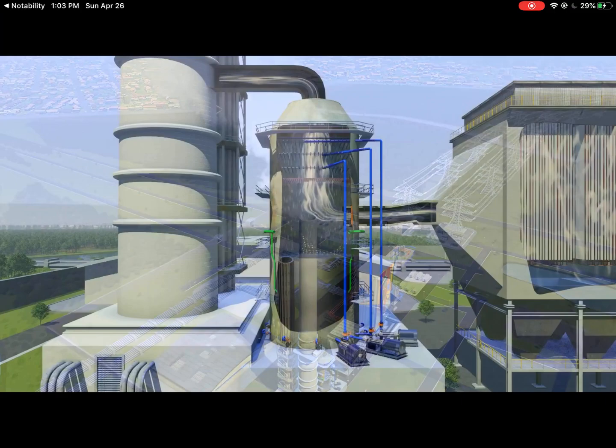So basically we're introducing the limestone or limestone slurry droplets from the top, and while these droplets fall downwards, they'll absorb the sulfur dioxide that's in the gas and then form some products. Finally, they'll settle down in this container. And then after we dry them, we can get gypsum. You can also see this device on the left, which is introducing air into this scrubber here.